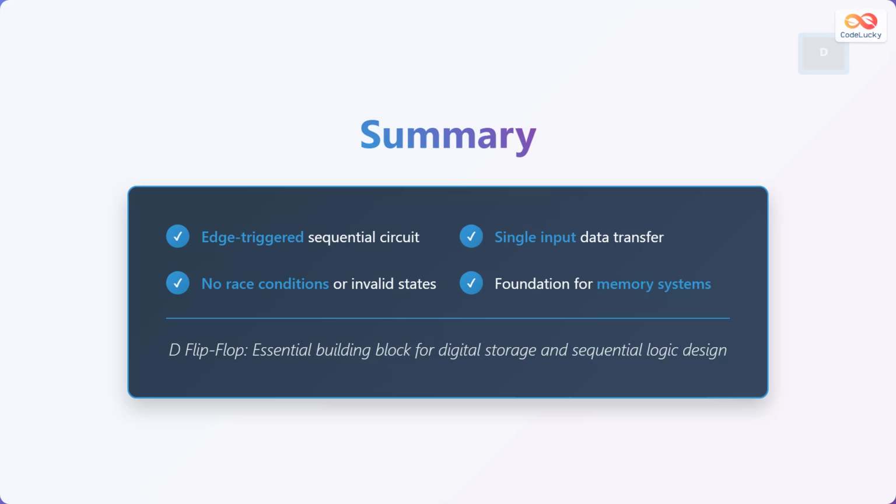To summarize, the D flip-flop is an edge-triggered sequential circuit, has single input data transfer, has no race conditions or invalid states, and forms the foundation for memory systems. The D flip-flop is an essential building block for digital storage and sequential logic design.